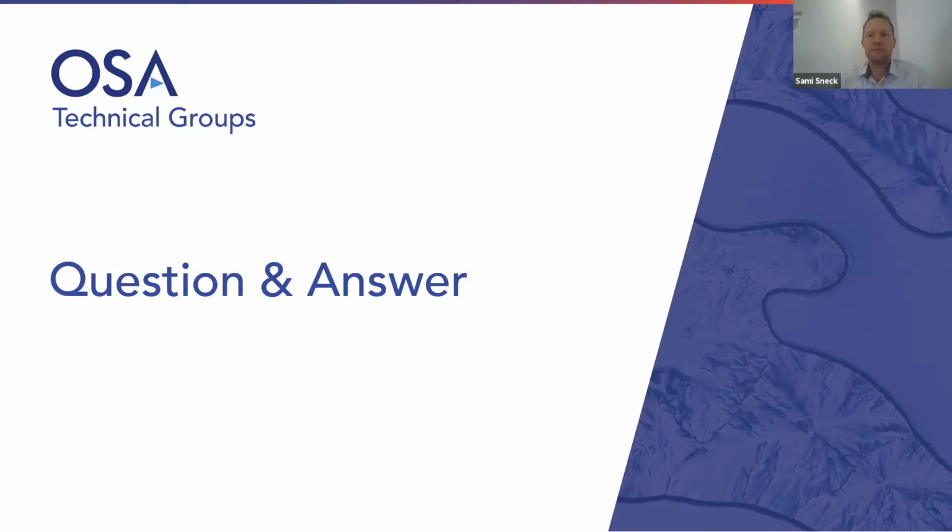Okay, well, maybe I can take this one. Thanks. Good question. The key is just to keep those two gases that we use as the precursors separated, not let them mix in the gas phase. So it means that the purge step is the key there. So we just need to have long enough purge times or efficient enough purge phases to keep those two gases separate.